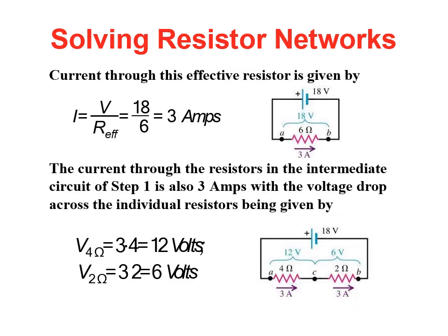Now that we know that the voltage drop across this effective resistance of 6 ohms is equal to 18 volts, what is the current through this effective resistor? It will be given by V divided by R, which is 18 over 6. That's the Ohm's law equation, V over R. So it gives us 3 amperes.